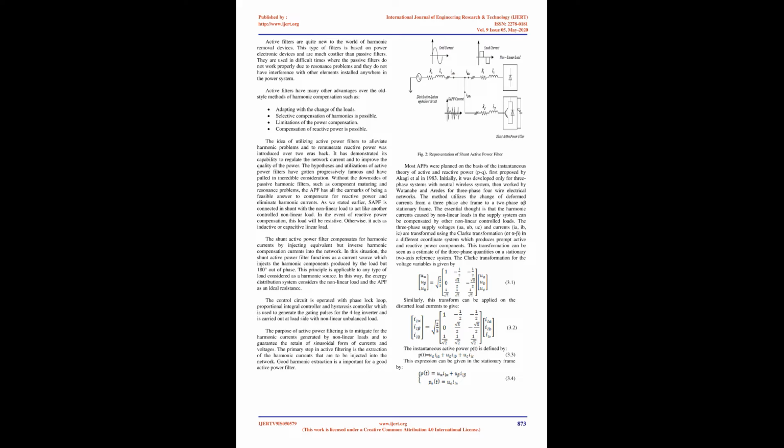The IEEE standard requires that harmonic distortion of the current waveform be restricted to 5%. However, some engineers believe that running a plant with such high harmonic distortion can lead to significant energy losses and shorten the life of equipment, and suggest that the total harmonic distortion should not reach 1.5% under operating conditions. Modern solutions have been proposed as effective solutions for eliminating harmonics from the electrical network in order to overcome the drawbacks of old-style methods such as passive filters.